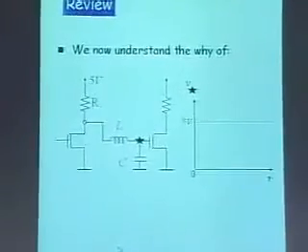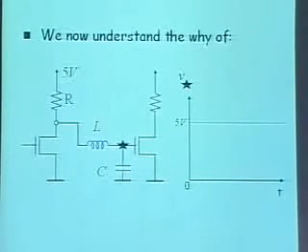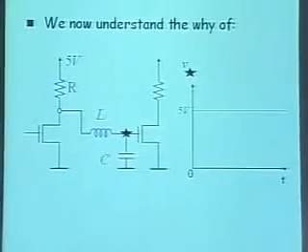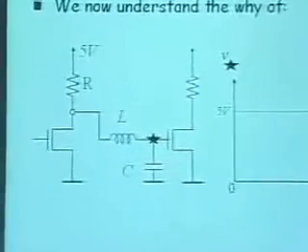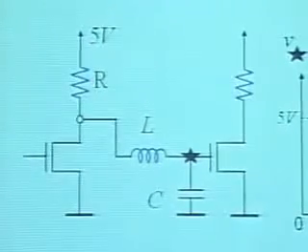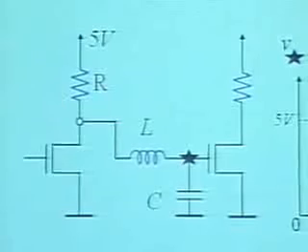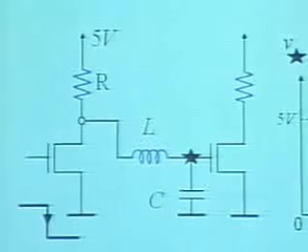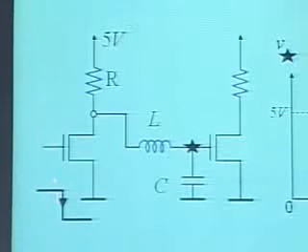In the last lecture, we talked about this circuit, and we did the same two lectures ago on Tuesday. So we had one inverter driving another inverter, and we said that the wire over ground has some inductance. CGS is the capacitor of the gate, and R is the resistance at the drain of the first inverter. And if you look at this circuit, that circuit formed an RLC pattern.